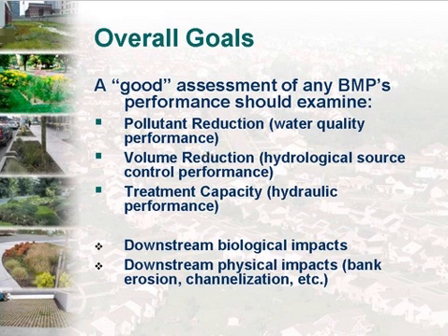Now, looking even more broadly, and when there's sufficient budget available to do it, and when there are factors that would compel this, we can also evaluate downstream biological impacts associated with a BMP, as well as downstream physical impacts. For instance, if you have a pond that you're monitoring and you haven't been careful with the design of the outlet structure for the pond, the receiving stream below that pond can actually be adversely impacted. The channel could be widening or deepening or both. So really, ideally, Nikos, we look for physical, chemical, and biological monitoring of BMPs.